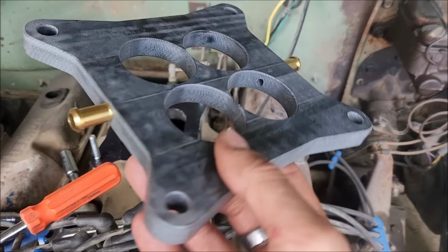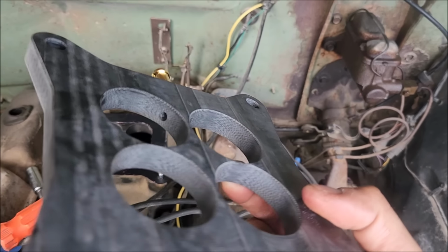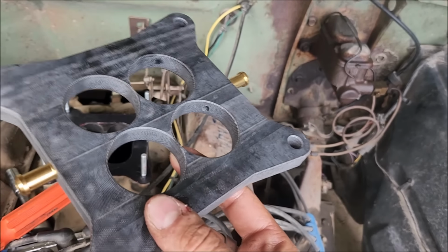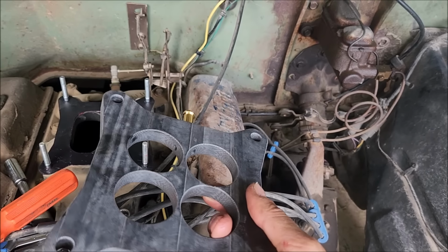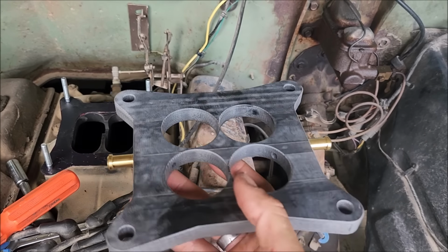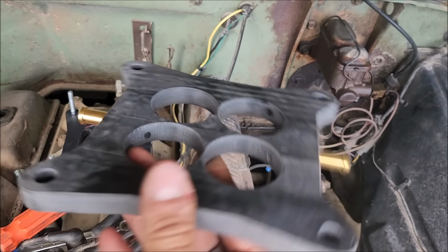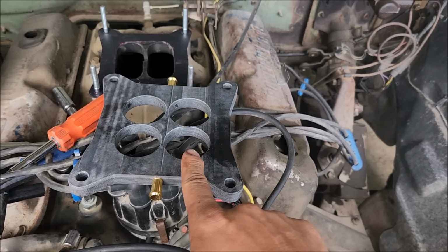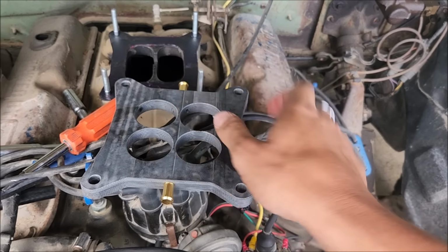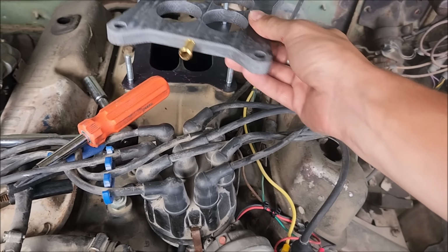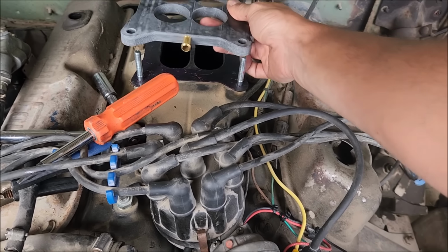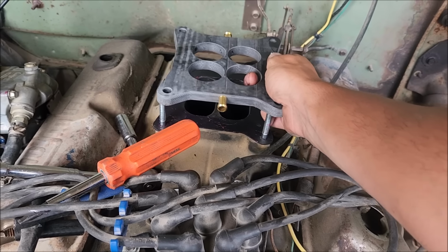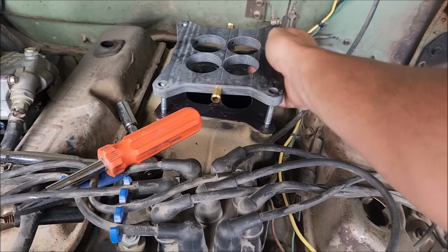We're gonna take our carb spacer and we're gonna look at it. These ports are actually angled up or down. We want them biased down, and ultimately we'll emboss this so you know which side is the top or the bottom. But I can see that the air goes in and then it curves down here. So this is technically the top. It can go either way. There's no particular way in that regard. And then we're going to install the spacer.